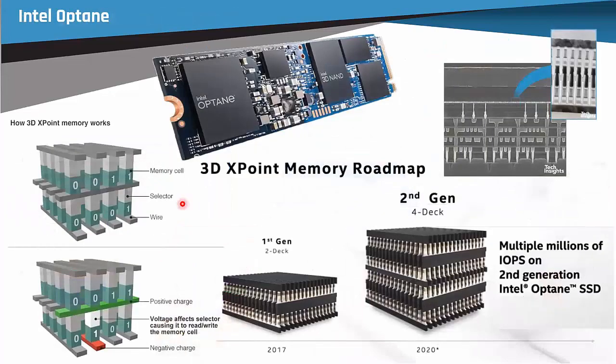With that, we have Intel, which came up with Micron, even though, as far as I understand, Micron kind of left this. They put out a product called Optane, which is phase change memory, which they actually sell as either instead of a DRAM DIMM or instead of an SSD, and you can even have it sitting on top of your chip, and it's really fast non-volatile memory. So it's really the first of these emerging memories that has come to a product that we can actually go out and buy.